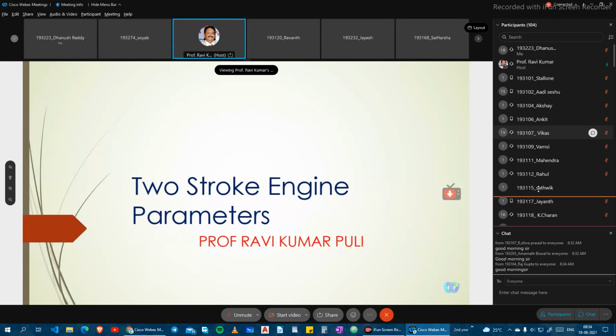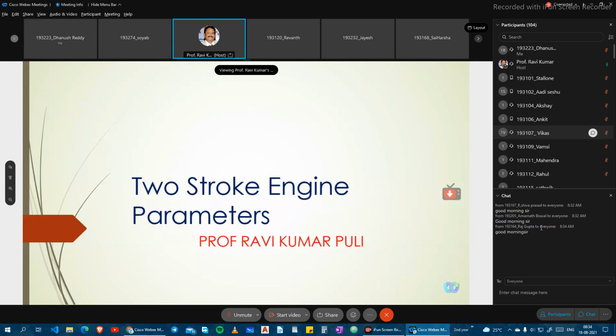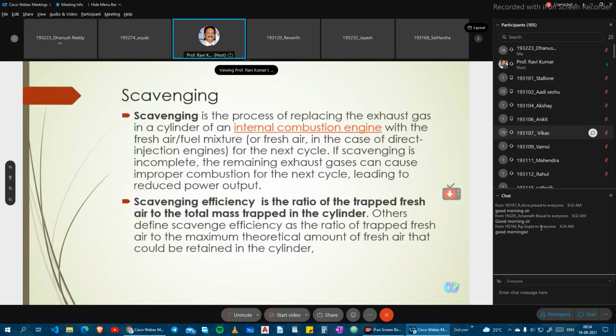In the upward stroke, in a two-stroke petrol engine, the fuel is taken in. We have a carburetor, which is a mixing chamber where fuel and air are mixed in a fixed quantity, and that enters through the crankcase through the inlet port. Whenever the piston goes up, the inlet port opens and the fuel goes up and gets combustion in the upward stroke itself. At the end of the upward stroke, the combustion takes place and the piston comes down, pushing it up. Then the exhaust port opens.